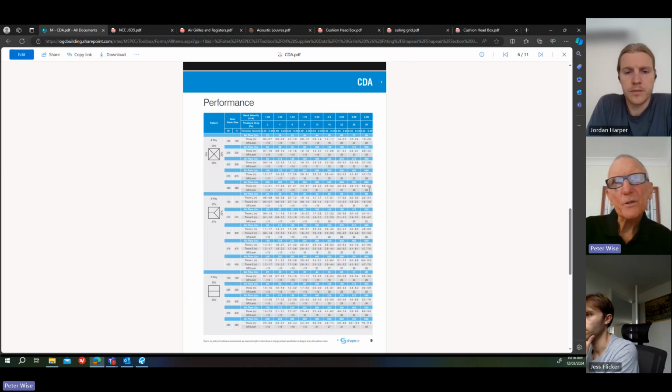Well, just to give you a bit of an idea, if you have 2 sound sources that are the same noise, it will add 3 dB. So if you've got all these noise sources around each other, creating the same noise because you've got the same airflow, then your noise level is coming up and up and up. Here's a bad example, but if you're in a group of people and everyone's talking, the sound level's going up and up and up. It's the same thing, those noise levels keep adding together to make it very noisy.